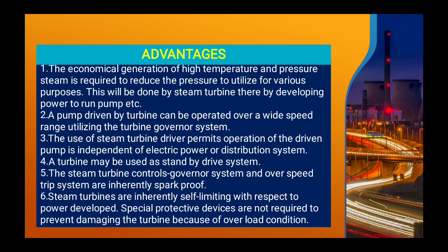The steam turbine control governor system and overspeed trip system are inherently spark proof. There are no electrical equipments used, so that is spark proof. Steam turbines are inherently self-limiting with respect to power developed. Special protective devices are not required to prevent damaging the turbine because of overload condition. So these are the advantages of the steam turbine.